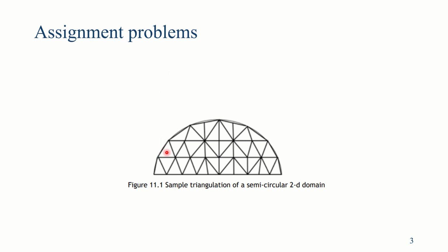We can say that it is in the form of some arrangement, but it is not a structured grid. Why are we saying that? In a structured grid, when we move from one cell to the next and identify the neighbors, there should be some common way of representing the neighbors.